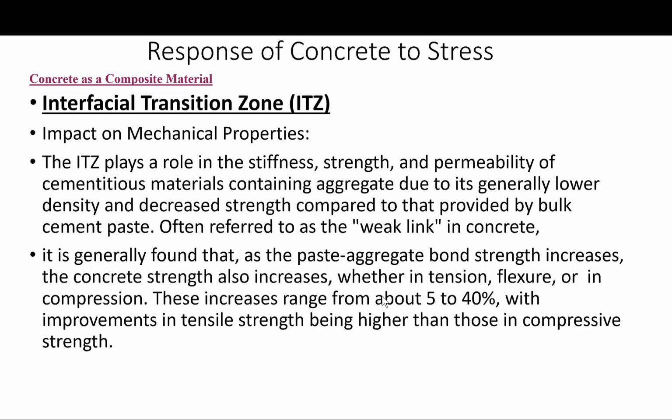So the bond strength depends on the surface characteristics or the roughness of the aggregate particles, on the degree of bleeding, the chemical bonding in some cases, and on the particular specimen preparation techniques, which is basically not easy to measure. So it is not possible to reconcile the results of the various investigations that have been reported because they're all over the place.